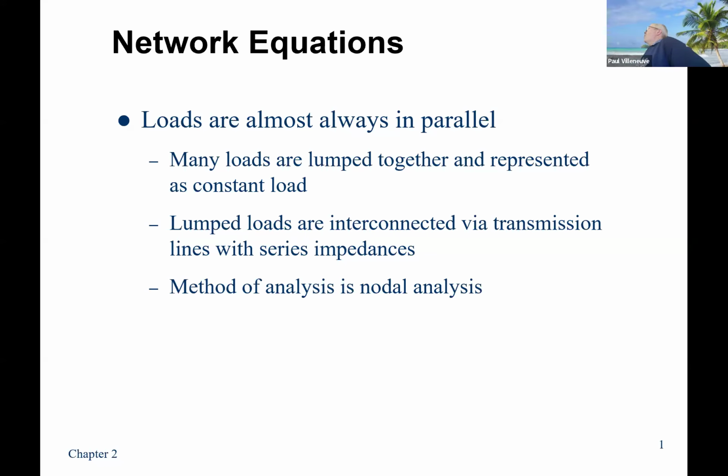And so really what we're going to be doing is building Y-bus, which is another way to say a matrix of all the system admittances. And we'll explain why admittances is the right way to go in a little bit. So that's all Y-bus is: building a system matrix that contains all the admittances, as long as they're correctly configured for that system. And once I build that, I'll be able to tell you gobs and gobs of information about the system.